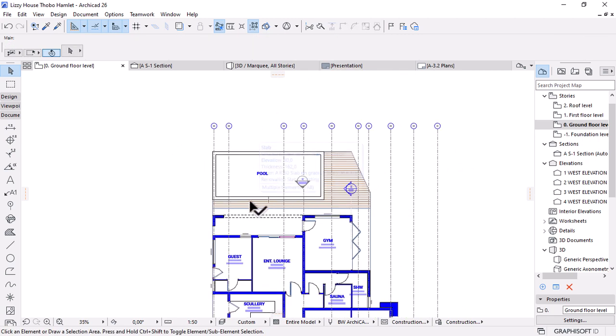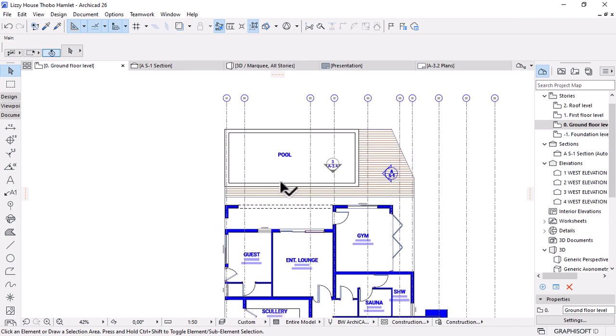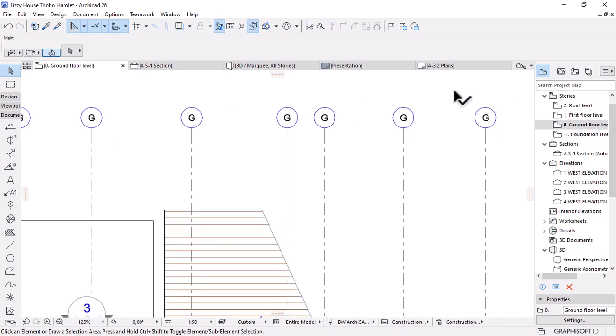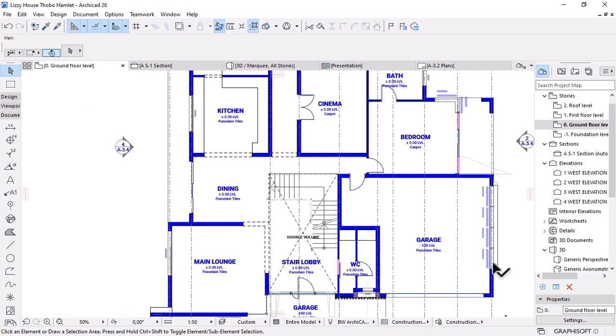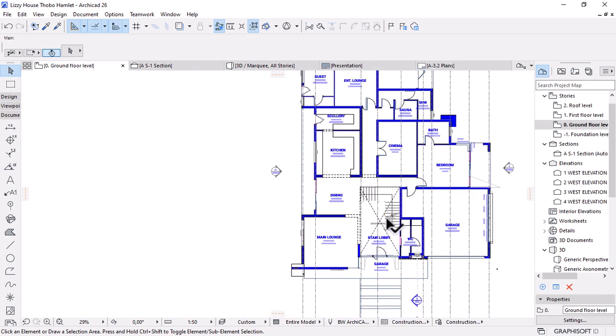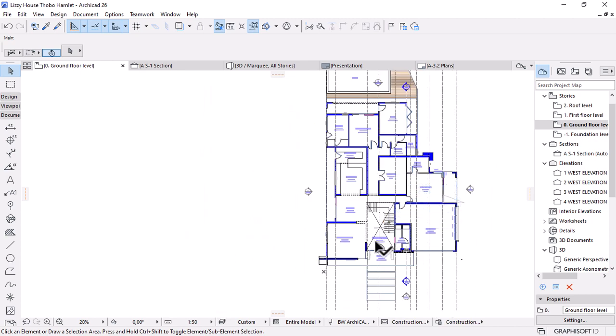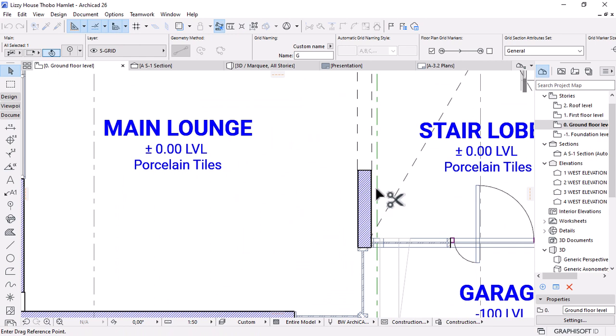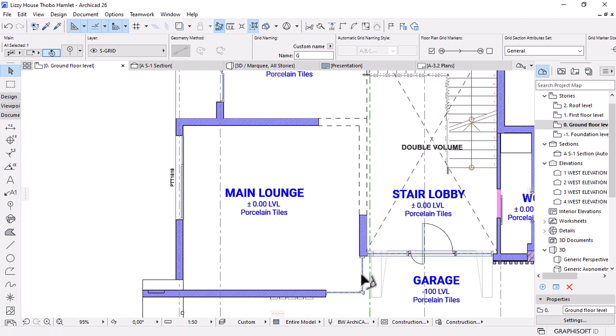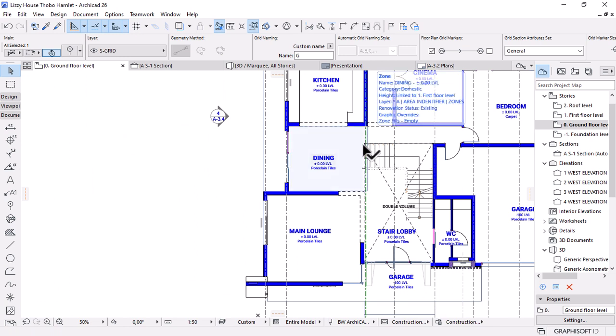What I can do, I think, let's make sure they are all placed vertically for all the vertical walls. I think they are all. What I would want is to make sure these walls were supposed to be inlined. I don't know what happened. Let me make sure they are inlined. You see, this is the reason why these grids would help.